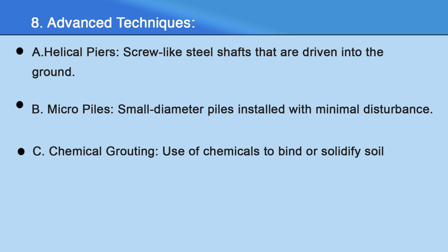Last method, that is advanced techniques. This is further divided into 3 techniques, that is helical piers, micropiles and chemical grouting. So, helical piers: a screw-like steel shaft is driven into the ground. Micropiles: small diameter piles installed with minimal disturbance.